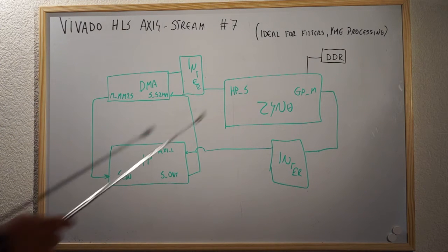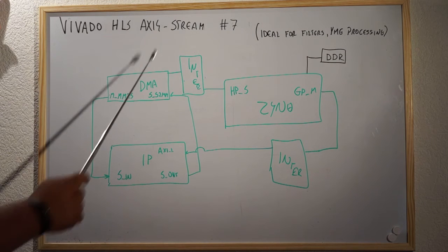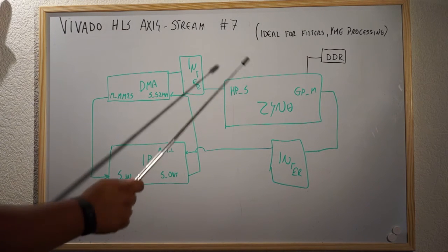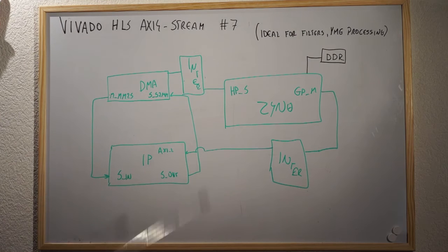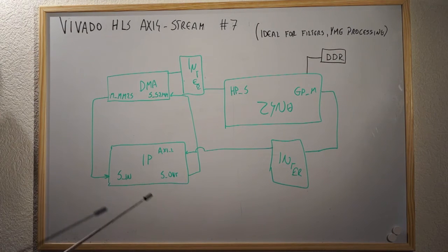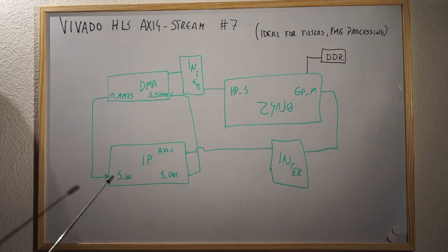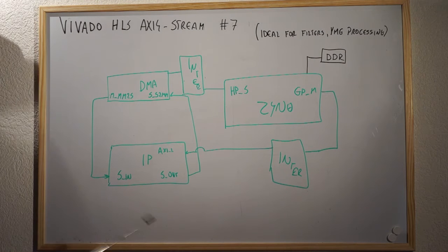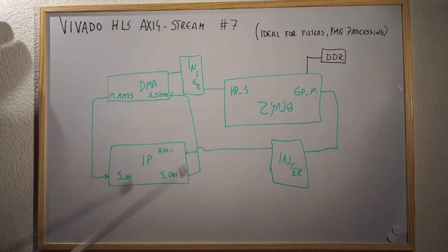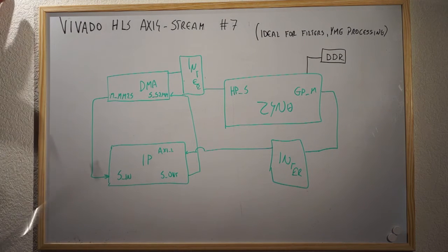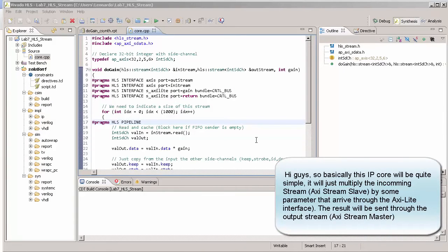So, remember again, use the AXI stream interfaces if you're going to create, for instance, a convolution filter, FIR, or really some kind of algorithm that falls nicely into this stream behavior, where you push some data in and you want to have some data out immediately.